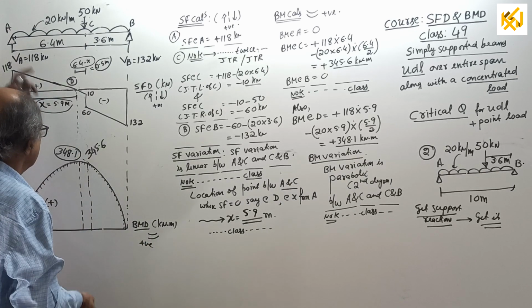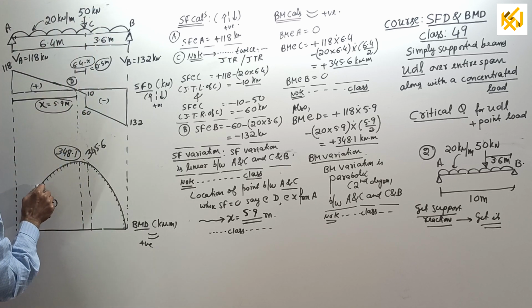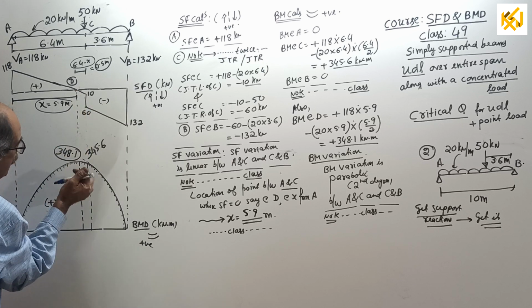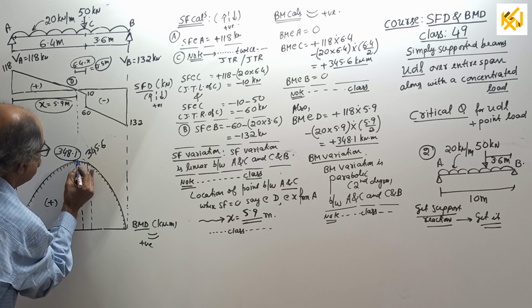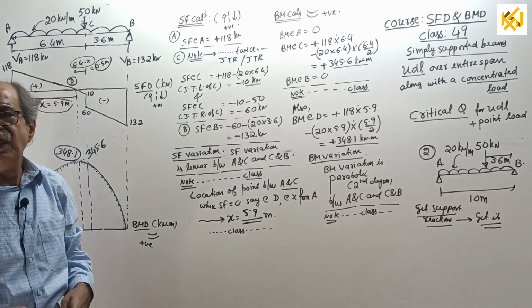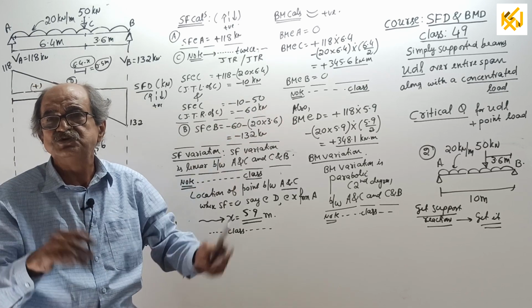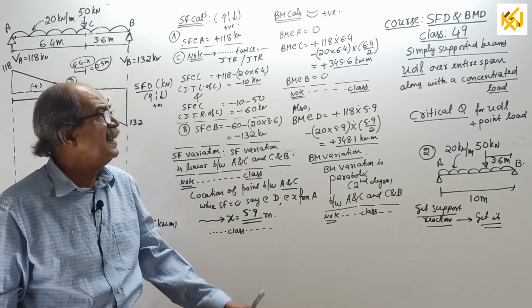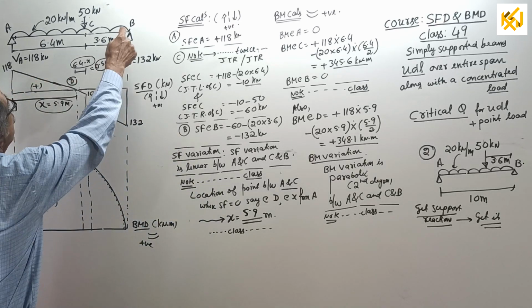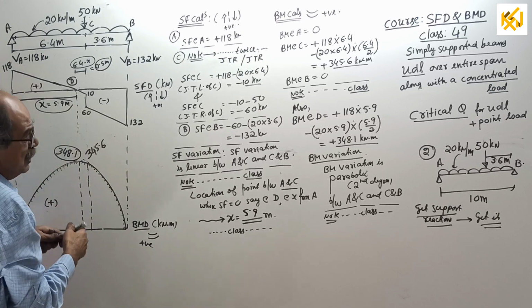So, a little exaggeration. Now, very important. A to C, one single curve. It should go this way, reach the peak value at this point, then slowly drop down. And if you draw a tangent here to this bending moment diagram, the slope should be 0. In the last class of this series, I will explain everything one by one on the board with magnified views, and I will tell many finer points there. That particular class is going to be longer, not like today's class. Then B to C, one variation. Now, again important. See, here not possible. I will tell you somewhere here.